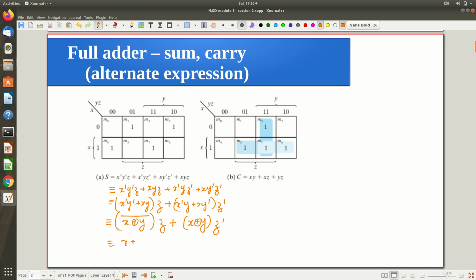The first one, that is X XOR Y XOR the second one, that's all. So the whole thing is now a very small beautiful expression you are getting, right? X XOR Y XOR Z. So this thing is a group, this is another one, and you know this XOR gate whether is associative or not, I have given you something in the assignment.